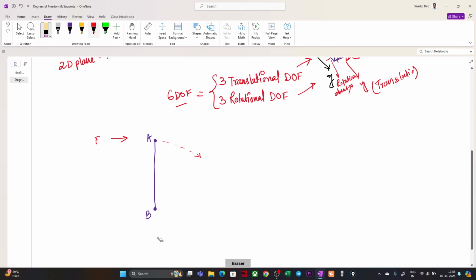So when we are saying that we have provided a ground here, what does it mean? That we have already restricted the movement of this line along this direction, along the vertical direction. Okay, this is in 2D space. Remember, this is in 2D space. I am saying suppose x and y. So we have already restricted the movement of this line along the y direction.